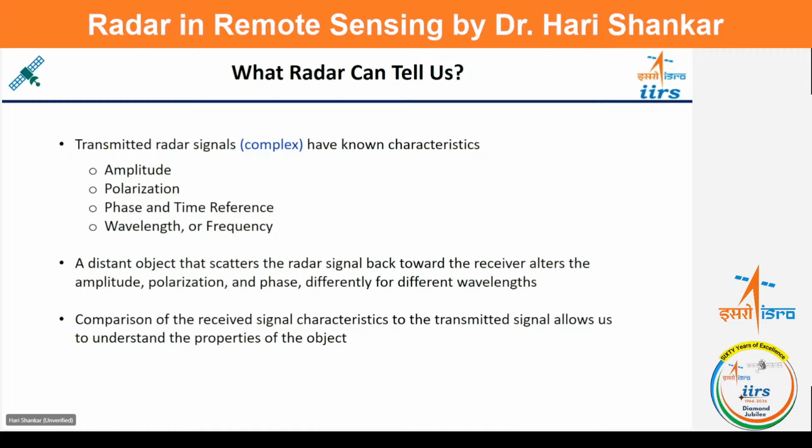But apart from that, we did not discuss that in radar systems we are using specialized electromagnetic radiation. The ordinary radiation we are not going to use. We are using a specialized one, or you can say polarized electromagnetic radiation. Yesterday we discussed different types of polarizations, like elliptical polarization, circular polarization, and plane polarization. Whatever signal we use in radar systems, they are polarized signals, whether plane polarized or circular polarized. But in space-based remote sensing, nobody has used elliptical polarized signals.